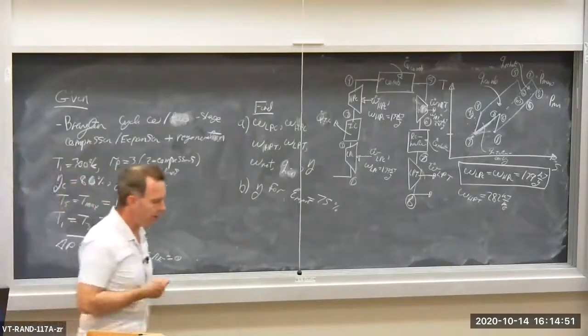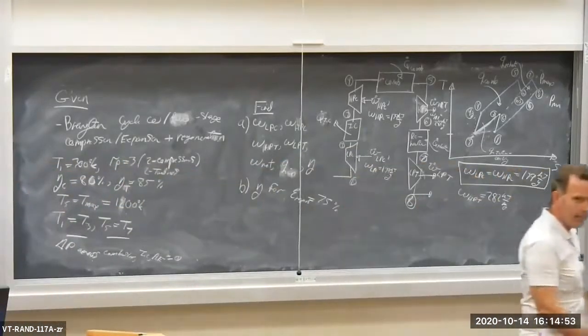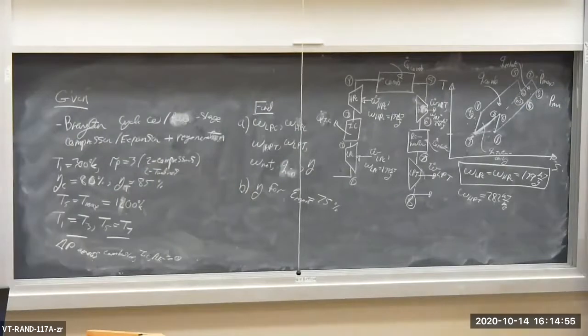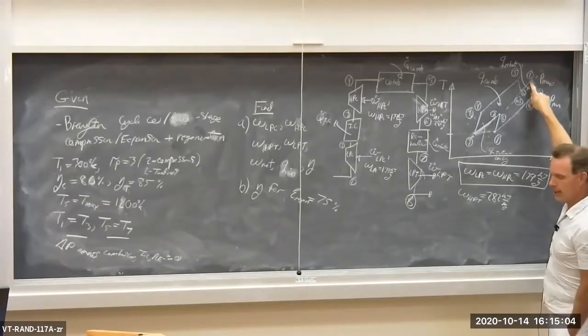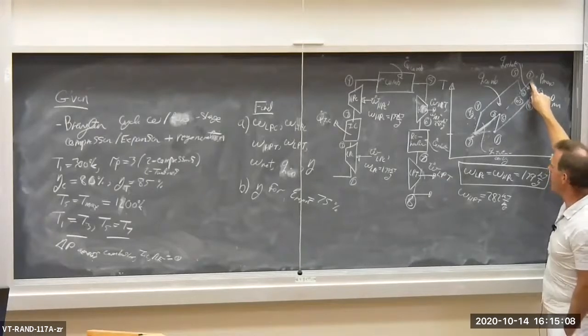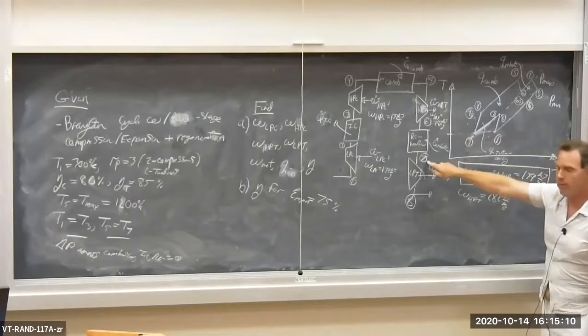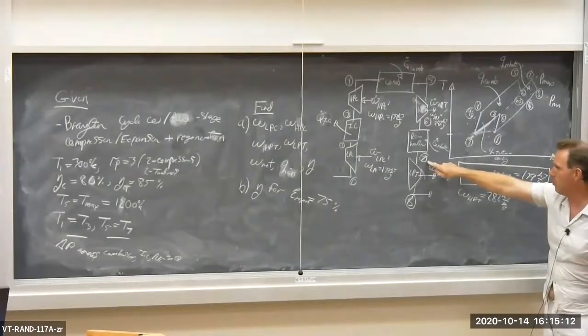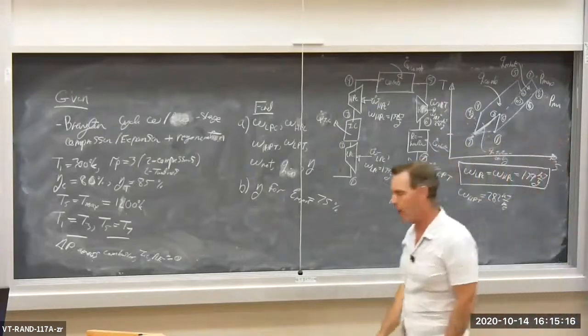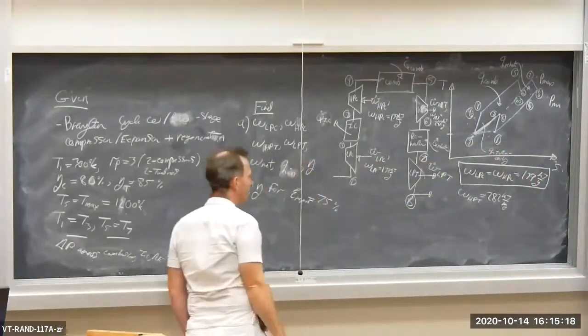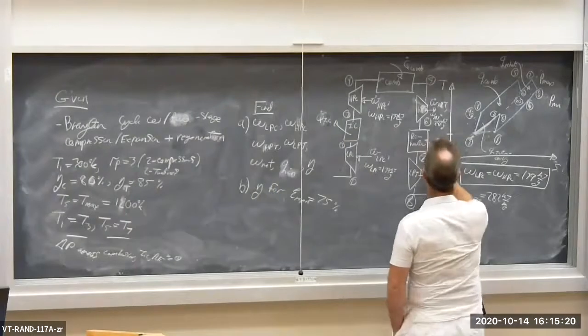All right, what about the low pressure turbine? Guess what? Same issue as for the high pressure compressor. We are told that the reheating increases the temperature of the low pressure turbine intake back up to the combustor outlet temperature. So T7 is equal to T5.